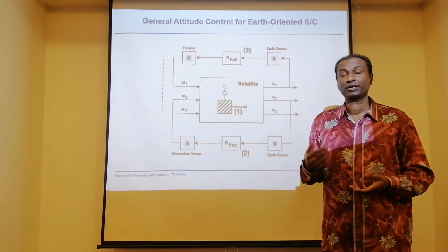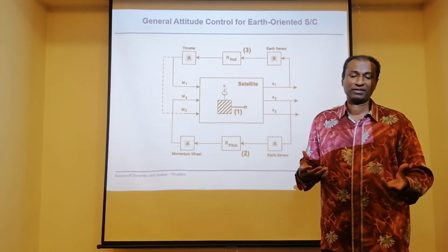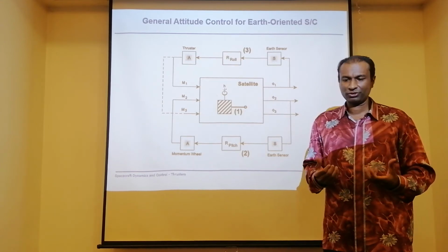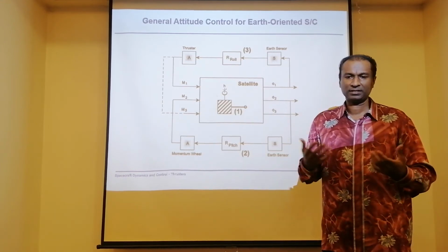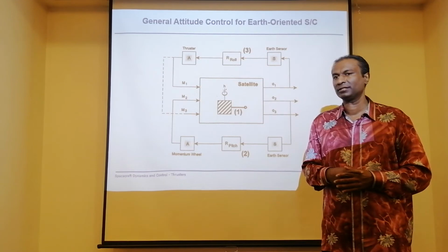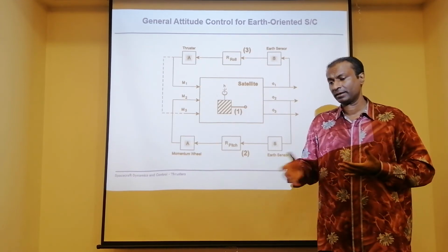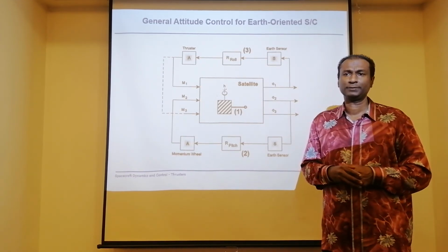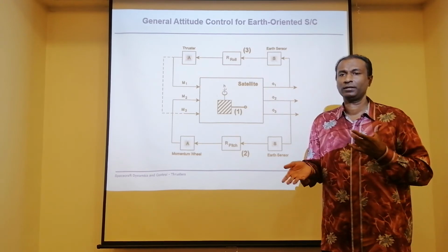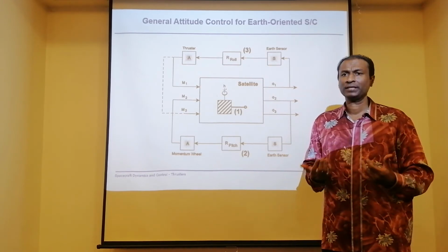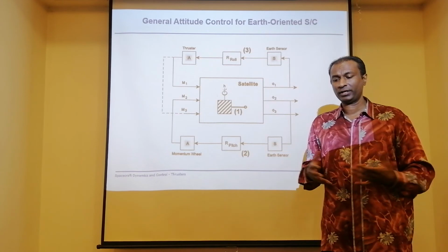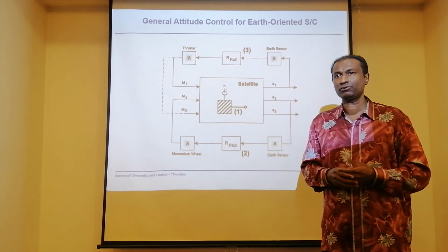Expensive in terms of needing to power the torquers and have the device. Then it's not good enough, because it gives a very high amplitude in terms of attitude. And you embark the options of the rotational actuators, reaction wheel and momentum wheel, and/or. And you have found that it is fantastic. It is giving us very good results.